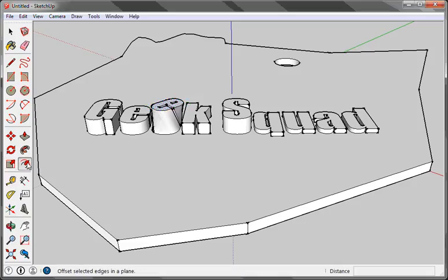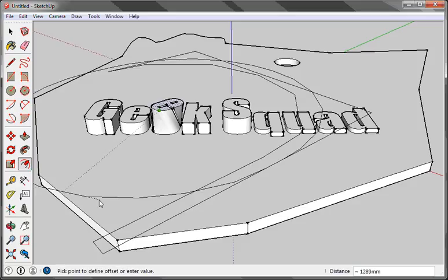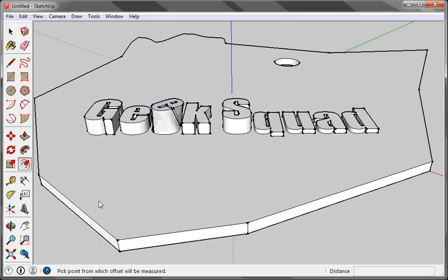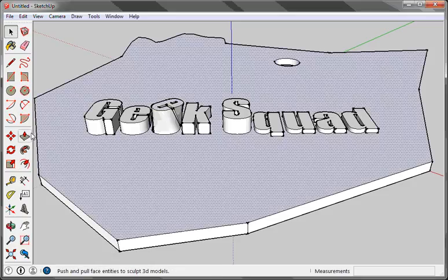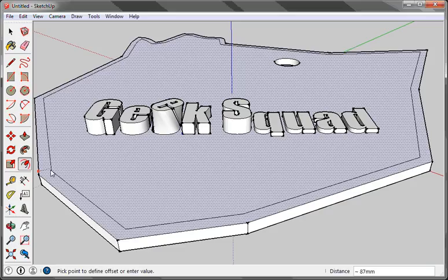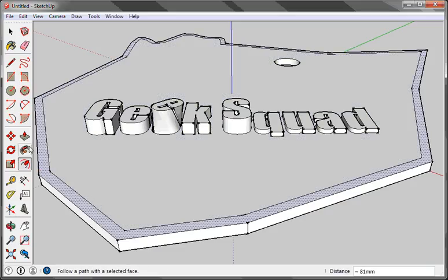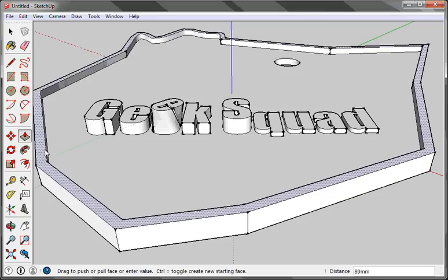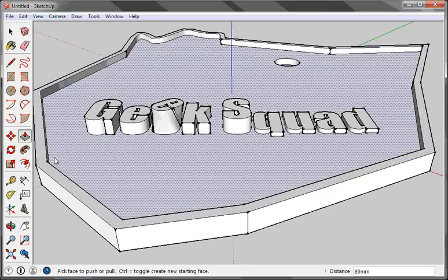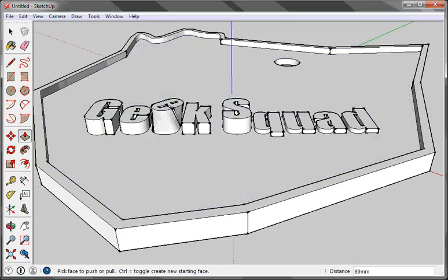One of the next tools that we'll want to do once we've finished is use the Offset tool to draw a small inner border on our shape. We can then lift that with the Push and Pull tool in order to give our shape a real border similar to what a keychain would have. Your students at this point will probably want an opportunity to use a variety of different colors under the paint bucket or have a chance to experiment with all of the things that they've learned.